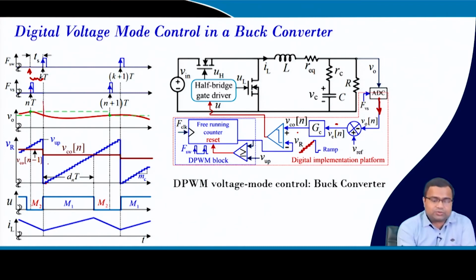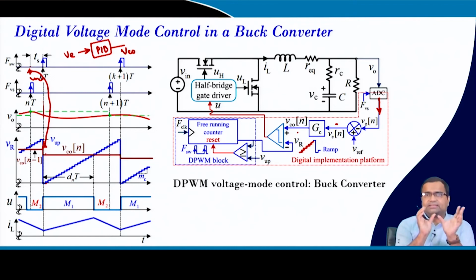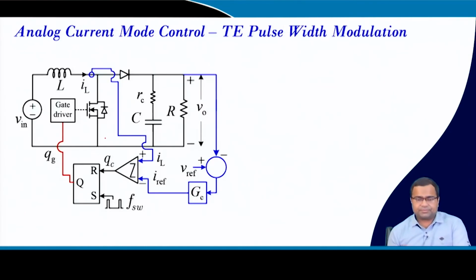and this is the actual switching. So, once you get the sampling data, this data will be computed and ready at this point, because this error signal will go through our PID controller, and the output of the PID controller will be ready here. So, it will take care of the ADC conversion time plus the PID controller computation time. Then we can do regular PWM operation.